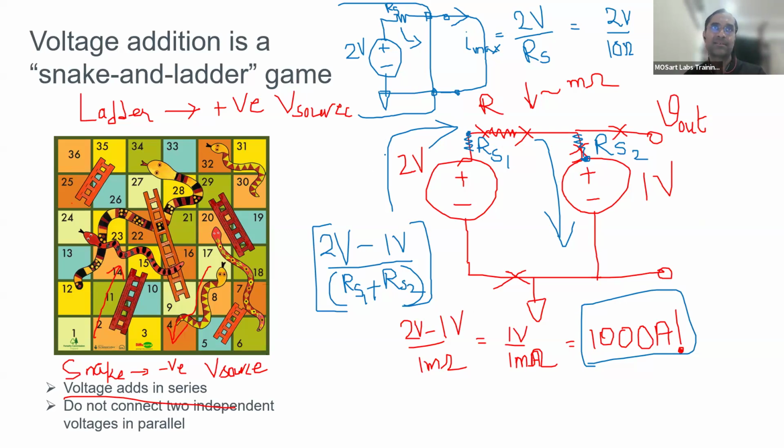Clear? So one doubt here: that car battery which we asked about, how are we connecting that one? The same thing happens. A car battery is a voltage source plus internal impedance. This is how a car battery is modeled. It's exactly the same as this: you have a voltage source and a series resistance. When a car battery is weak, the voltage source has a smaller value.